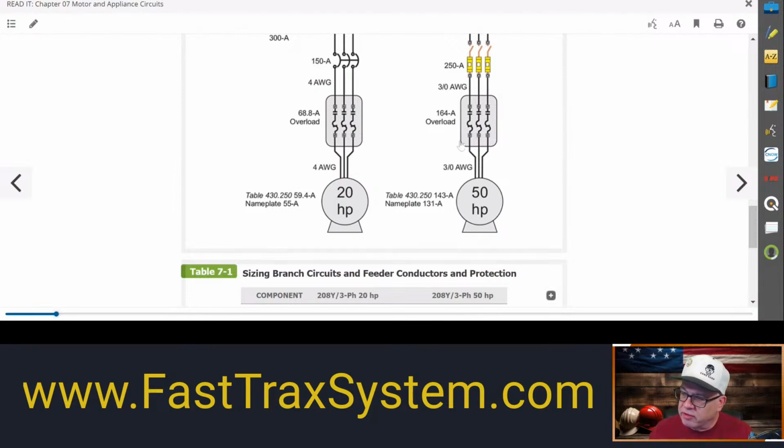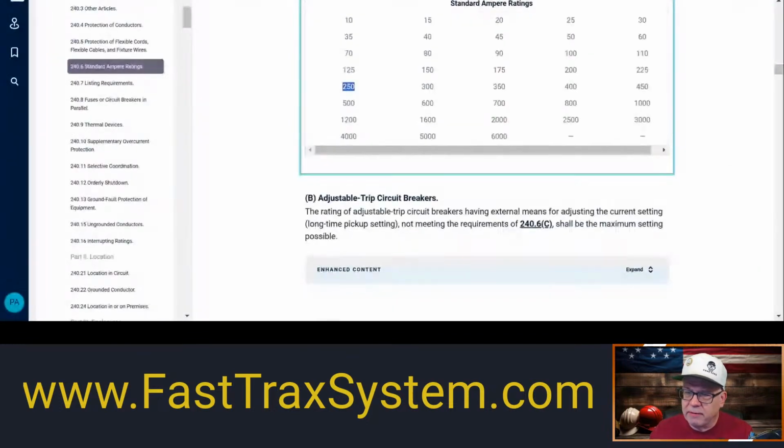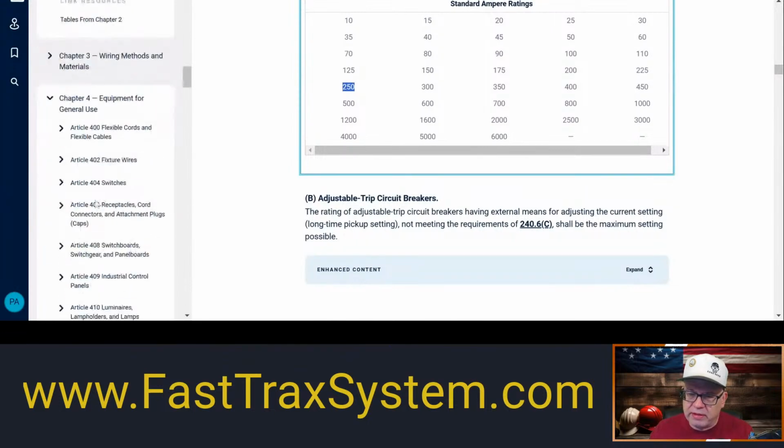As far as the conductors, same concept as we did before. We're doing them at 125%, in accordance with 430.22, because we're just doing this single motor here. In that case, it's the FLC, so 143 times 1.25 gives me 178.75, so we'll say 179 amps. Obviously we're going to be in the 75-degree column, so let's go to the NEC and we'll go to 310.16.